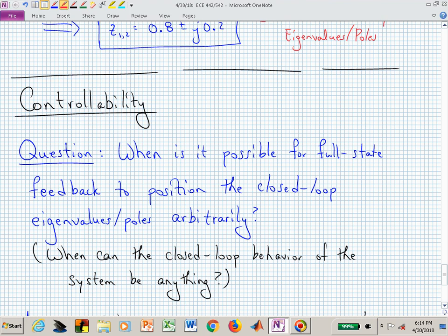But if you put them somewhere on the unit circle, then they're going to just continually oscillate back and forth. The period of that oscillation is going to be influenced by the angle that those poles make with the positive real axis. That would influence your theta sub d, which is radians per sample. That's how you oscillate in your system response.